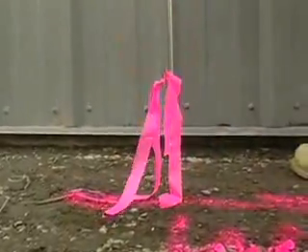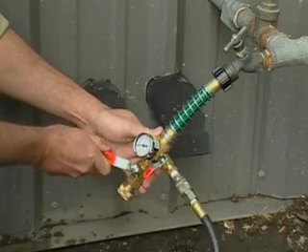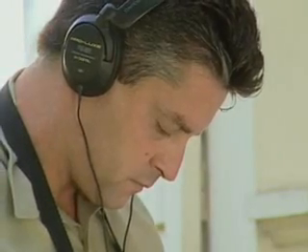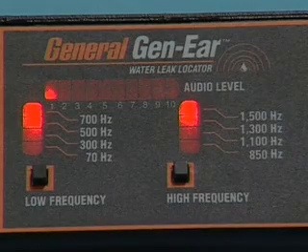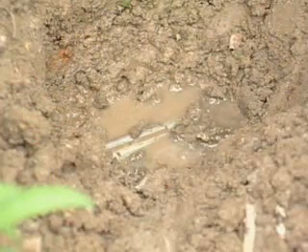Once you've pinpointed the leak and marked its location, double-check your mark by turning off the air valve on the SAM while listening to the marked area. If you're in the right place, the leak sound should dissipate. This assures that you found the leak, not some other outside noise.